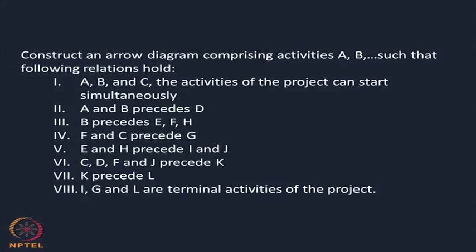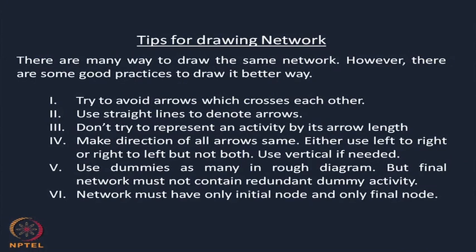We will see afterwards also when we are solving the problem by the critical path method. Just see quickly the tips for drawing the network. Number 1, try to avoid arrows which cross each other. If possible, always try to follow it. Use straight lines to denote the arrows. Do not try to represent an activity by its arrow length. Please note this one.